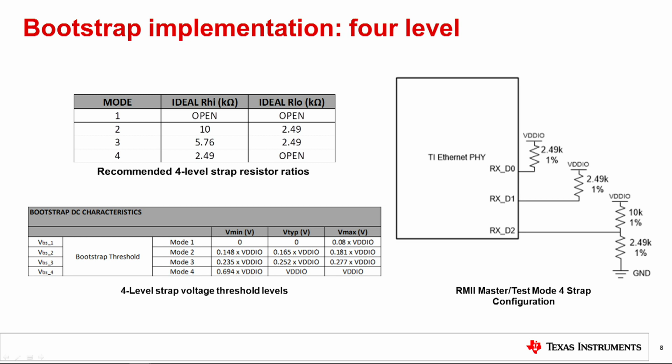Referring to the recommended resistor ratios, you will find the appropriate resistor values to place each strap in the desired mode, and you will find yourself with the strap configuration shown. Again, as a sanity check, you may want to check the voltage on the strap while holding the device in reset to ensure the PHY will be set to the correct mode.